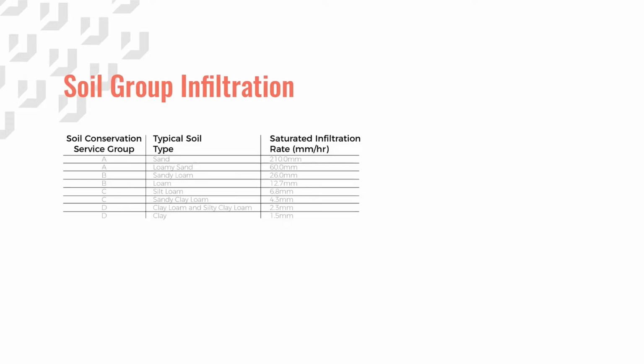Installing a permeable paver system above porous soils allows for rainfall infiltration, reducing runoff and flooding. Moist soils, even clay, allow for some infiltration. Soils with high porosity, such as sand, can have a higher infiltration rate than the actual rate of rainfall. For example, if it is raining at a rate of 2 inches (51 millimeters) per hour and the soil has an infiltration rate of 4.5 inches (114 millimeters) per hour, the soil will absorb water before it can run off.